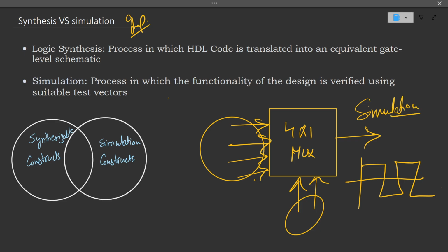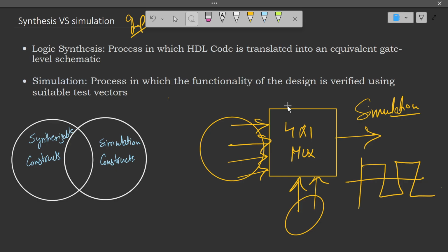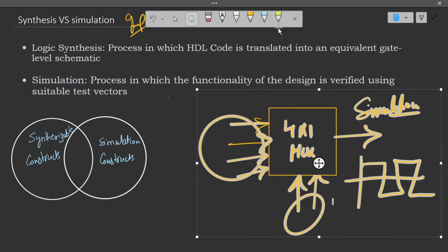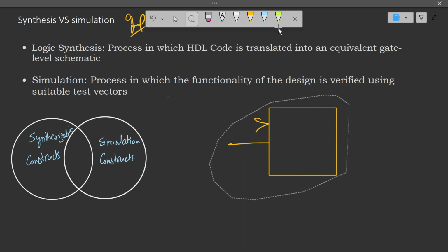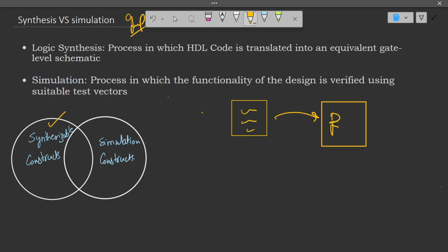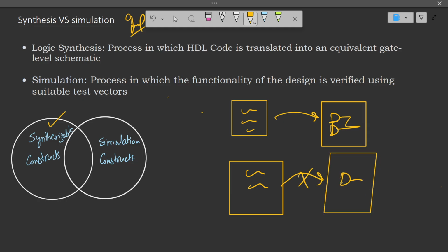In the Verilog language, it provides us keywords. Some of the keywords are synthesizable, meaning those keywords can be converted from textual format to the gate level representation. But some keywords cannot be converted to a gate level design.